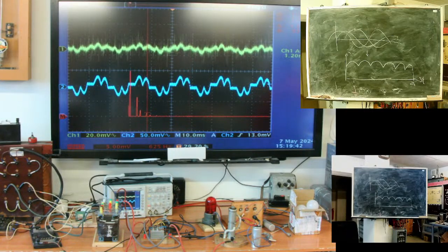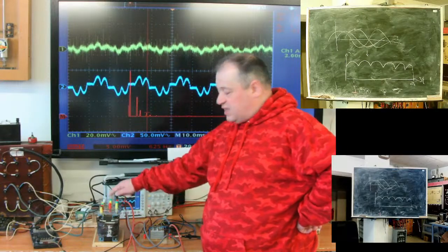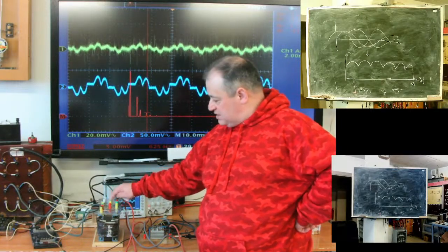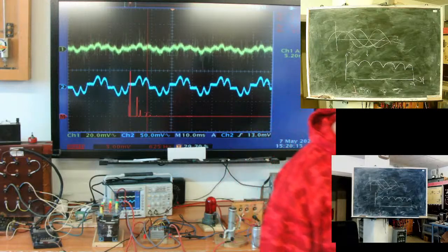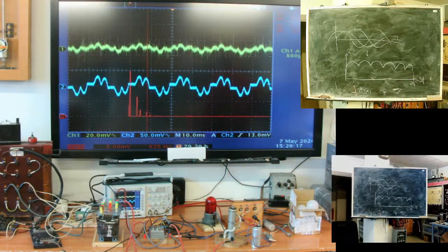Why? Because you have a powerful, let's say, it can also be a solar plant, but you have a powerful DC side. Actually, it's some kind of drive. Transformer, it's okay, fine. But since you have a full bridge, center of the star not connected, third harmonic cannot flow.